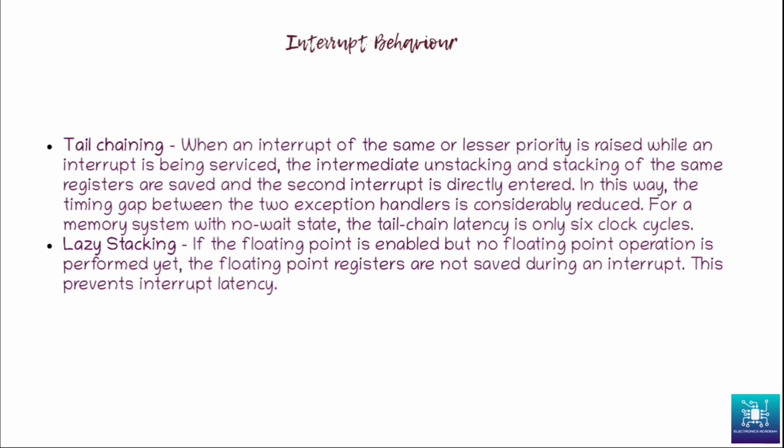What happens is, if an interrupt comes in at that point, the stacking happens for the shorter number of registers, because Cortex M4 detects that no operation happened for the floating point registers. So why stack them and waste clock cycles? It just leaves out the stacking of the floating point registers and goes ahead with the shorter version of stacking. So this again saves a lot of clock cycles. Tail chaining and lazy stacking are actually to reduce the interrupt latency in Cortex M4.